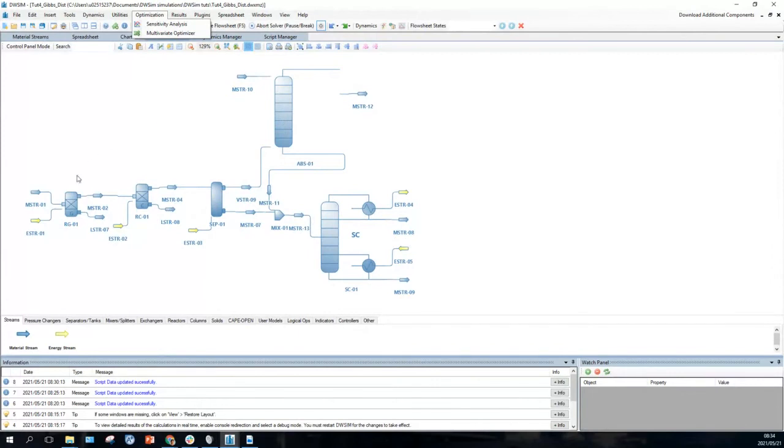So what we want to find out is what temperature. We chose a temperature so that we got 600 kilograms per hour coming out here, and then changed that because I put in the absorber. I see it's now 475 kilograms an hour, but never mind. We're going to try and optimize how much product we're making, which is the methanol.